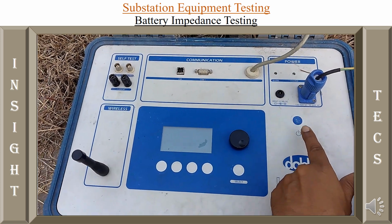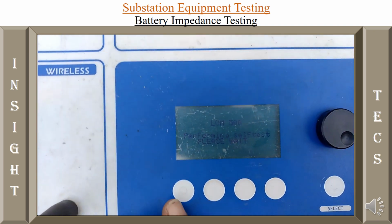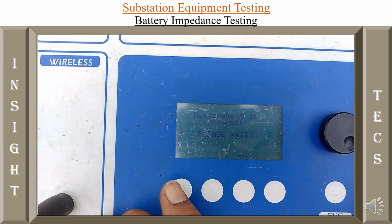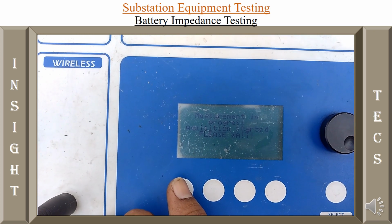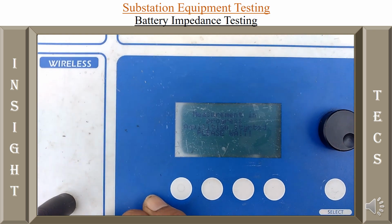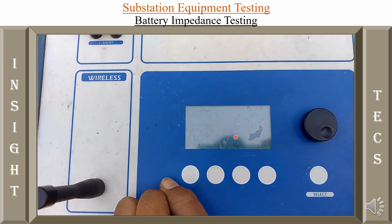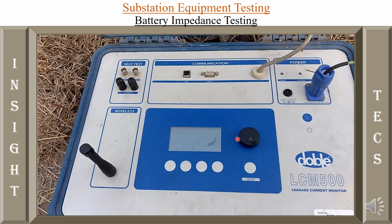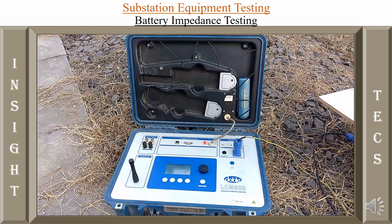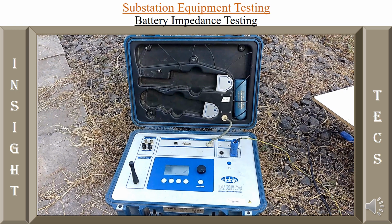Now let us turn on the kit. It has to be turned on only after proper earthing is done to the kit. You can see the LCM kit has started. We will click on the measure and run button. Measurement is in progress now, and you will be able to see the results on the screen after the measurement has been completed. 52 microamperes and 833 microamperes is the reading. So that is the leakage current that is flowing through this LA.